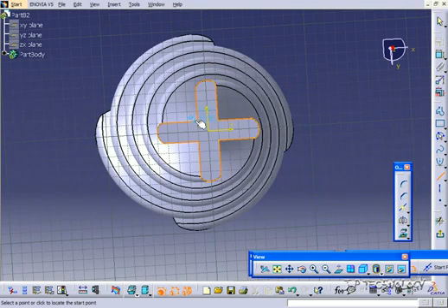So from that, you're able to create sketches off of these projected lines, and they're going to be precise and they're going to be consistent with the rest of the part. So rather than guessing, now you've got these edges that are there for you to use and to create your sketches from.